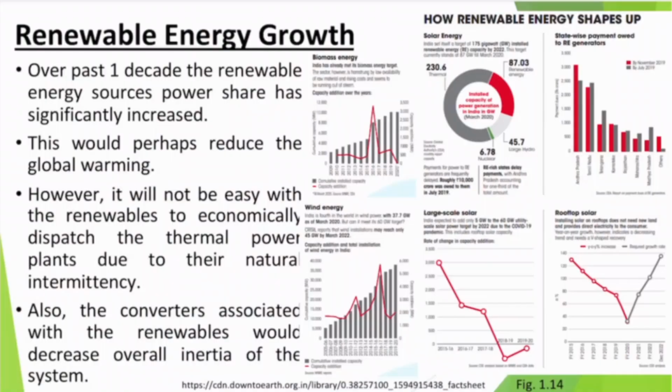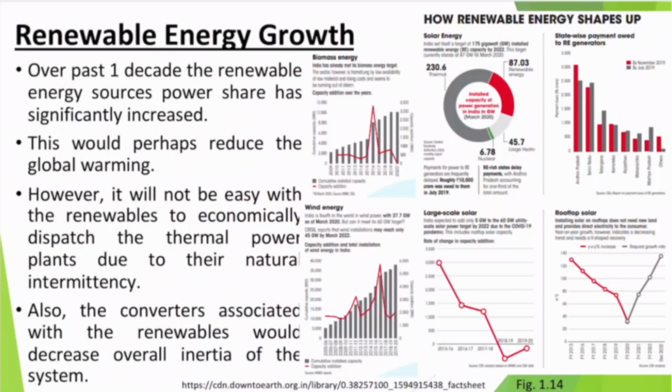So if you put a lot of solar power plants in any power grid, then probably you are reducing your inertial energy, which is not good. So to my understanding, we can certainly increase our renewable energy, but we cannot completely get rid of rotational energy systems such as thermal or hydro. We need to have some of them to support my renewable energy. So we have identified that there are two major challenges. One, the renewable energy which is not fixed, which is intermittent in nature, and also it fails to accumulate huge inertial energy, which also will be a challenge for thermal power plants to take a call on the amount of generation that they have to produce at a given point of time.